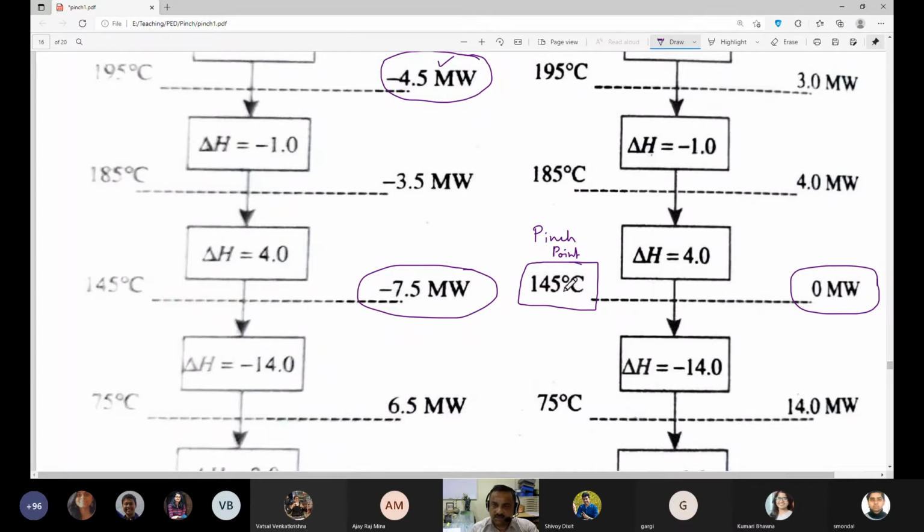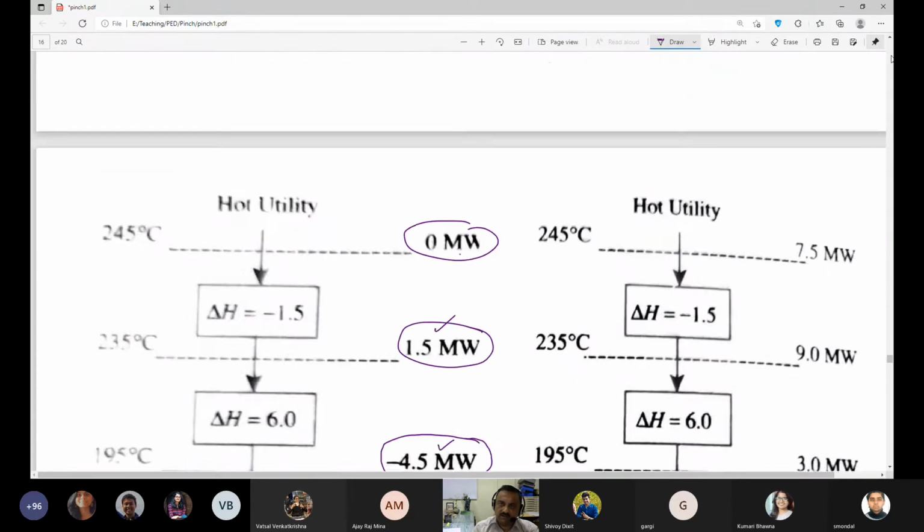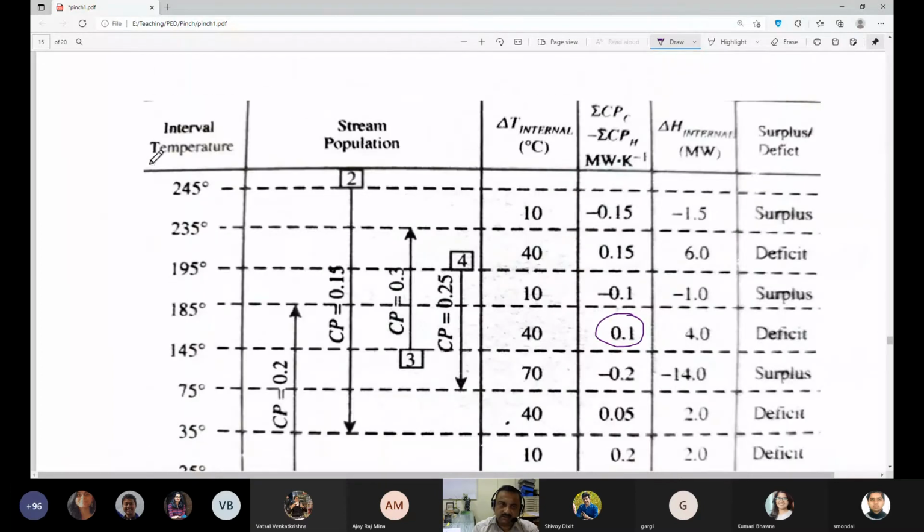So this is showing the average. So this is the pinch point. You can come up with this pinch point even without considering the composite curve. Essentially what you have done is you have changed the temperature values. You know for sure that delta T mean is going to be 10 degrees. Then you lowered the composite curve for the hot stream by 5 degrees, and jacked up the composite curve for the cold stream by 5 degrees, so that they meet at one point. And now you want to know where they meet, and you found that they meet at 145 degrees centigrade.